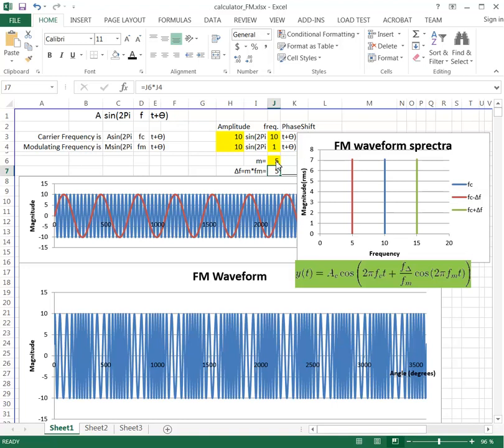So we can see how our frequency is modulated according to our modulating waveform here. When the modulating wave has a high value, in this case plus 10, our carrier frequency is altered to be the lowest possible frequency. When it is down here and we have an amplitude of minus 10 on our modulating wave, our carrier wave is operating at its highest frequency. So our modulating wave here is encoded on a carrier signal, and the frequency of our carrier signal is adjusted accordingly. And this is our basic FM signal.